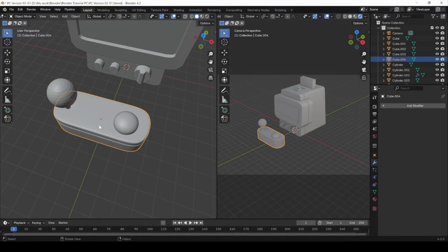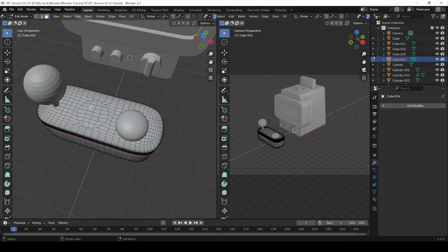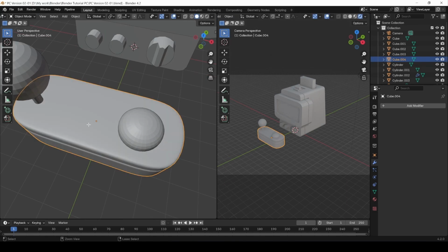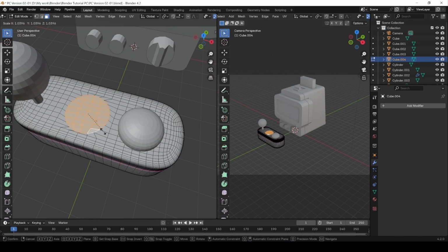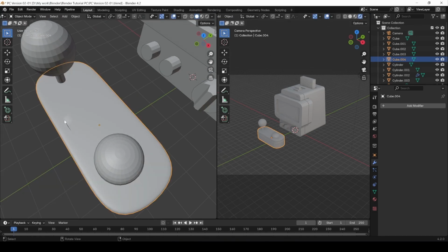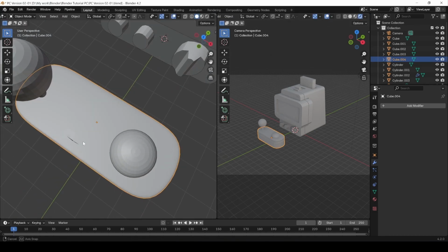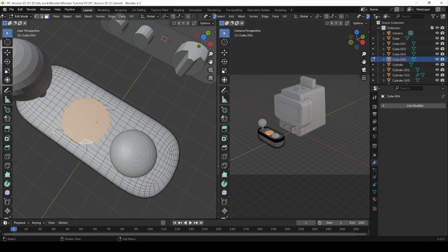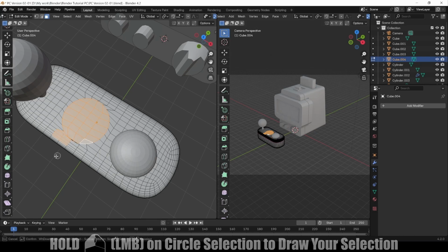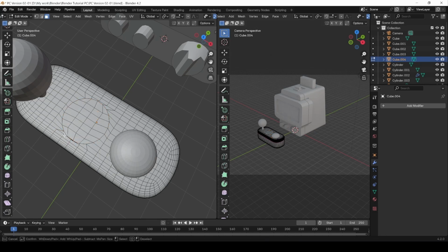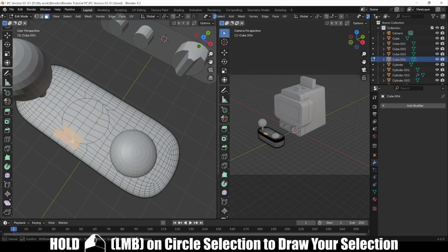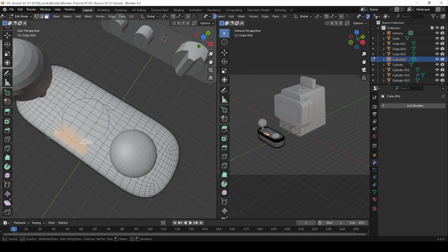Okay, and as you can see, it looks awesome. Now you can select these faces. Like, what if it was a little bit like that, which was intersecting with this, and you had this artifact right here? What do you do in that case? Well, let me show you a tool. It's a good chance to show you this tool. What you do is basically enter a C selection, and you just select this and select these small faces right here that are having the problem basically.